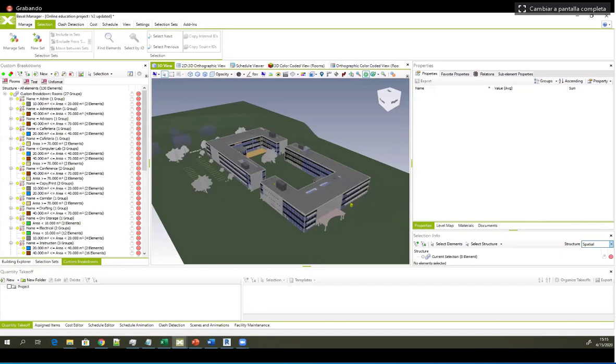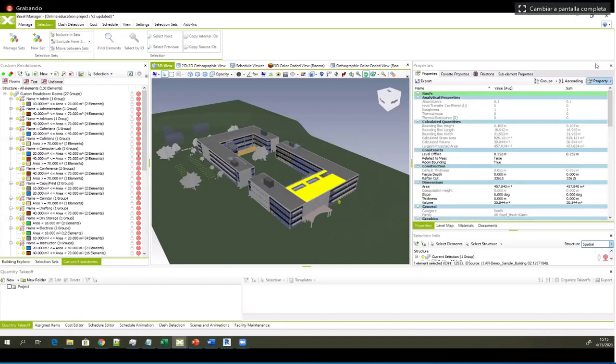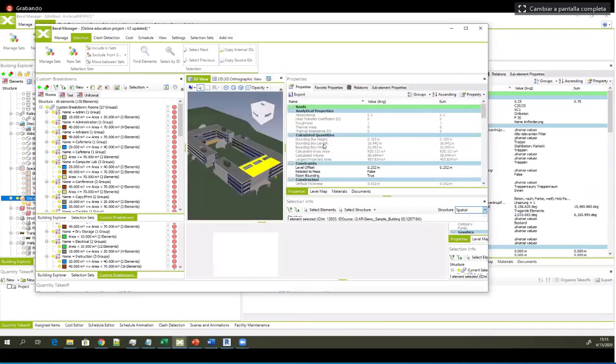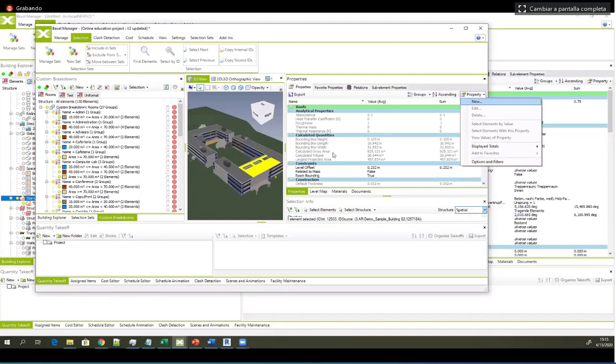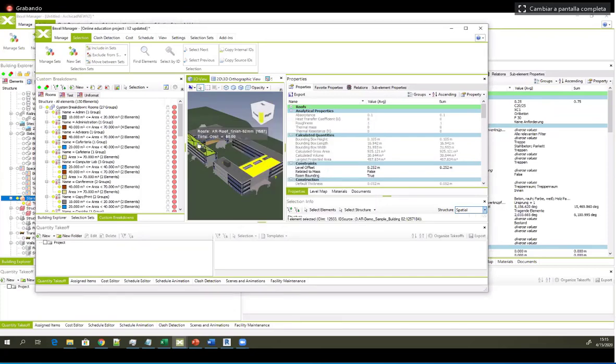How will the newly added properties be exported to IFC? In which class of IFC? Well, if you're just talking about the properties, they will be exported in the same way as you added them. You're specifying the property type, is it numerical, length, area, textual, or different types of properties. So these are going to be mapped according to that automatically.